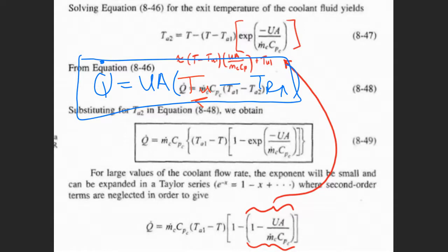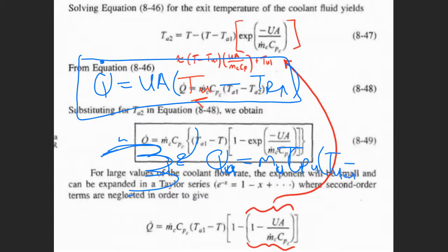It says you've put so much in there that the energy carrying capacity is so huge that it doesn't matter the amount of heat that flows to it. It can absorb it without really changing its temperature. So from the perspective of Q of the cooling medium, I've got M of the cooling medium, the Cp value of my utility, and the temperature of the utility out minus temperature of utility in.